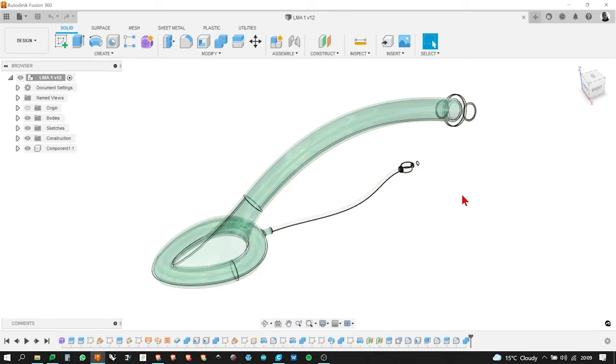That's right, but I could have done that as a solid body, couldn't I? I did it as a surface for a particular reason. Same wall thickness, absolutely. So instead of having to model the whole thing as a solid, perhaps then shelling it, which I could have done, perhaps it made more sense for me to do it as a surface and give it a thickness. So that was a bit of surface lofting, surface sweeping.